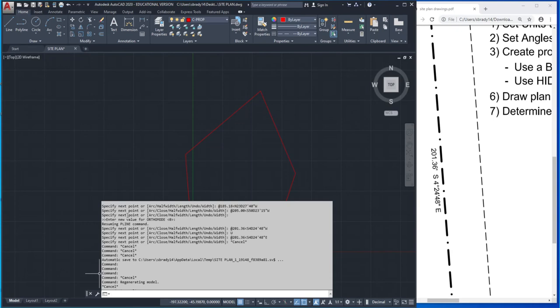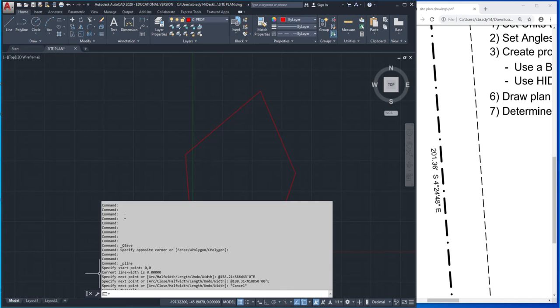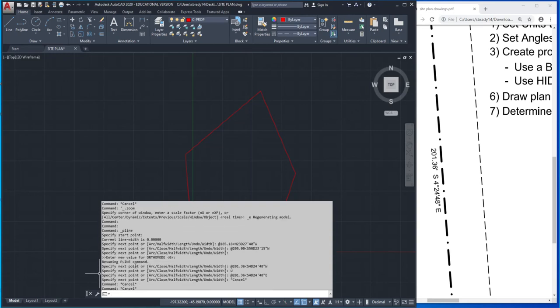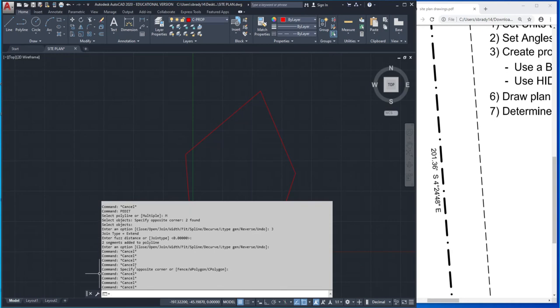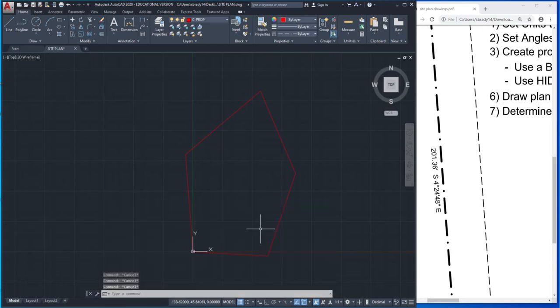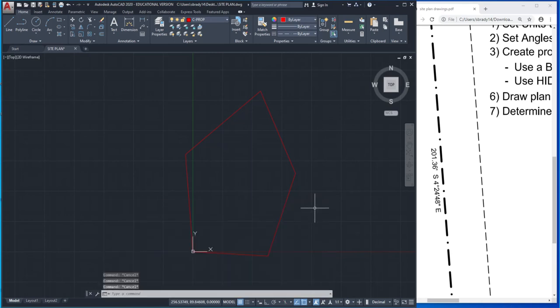So I can see what's happening. These are all of the commands I've done. These are escapes. This is a save. This is a polyline, right? You can see everything that you've done here. Units. I'm just rolling my roller to find them, right? But I can look there and see what's gone on too, okay? I can hit escape and it goes away. F2, escape. It's what's called a list, all right? It's a list of commands that you've just done.